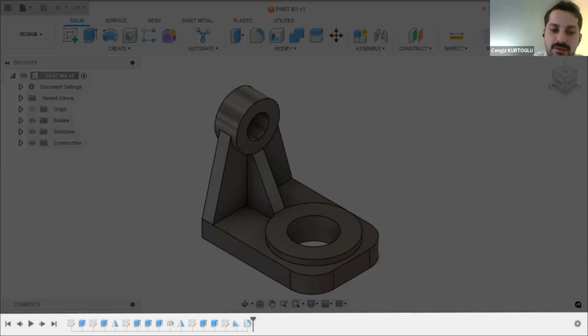Normally it'll start with 0. For example, I already created a sketch, then an extrude, sketch, extrude, etc. You can always return back to modify these parts, and you can change some features or suppress some features to modify your parts from the timeline.